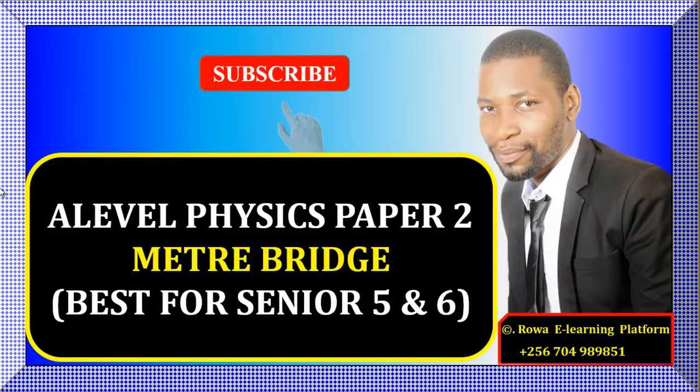Then here, current flows when the switch is closed. Current will flow, and at this junction it will split. I1 will go through this, I2 will go through the resistance wire. So I1 goes through, let's say R1 and also R2, and I2 goes through this uniform resistance wire. At this junction it combines to go back to the source. This is what we call the left-hand gap, and this one we call the right-hand gap. R1 is called the resistance in the left-hand gap. R2 is called the resistance in the right-hand gap.